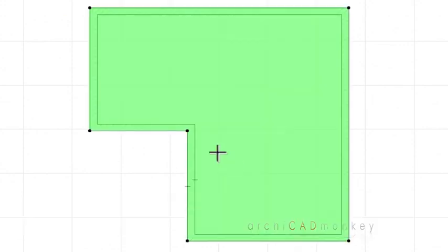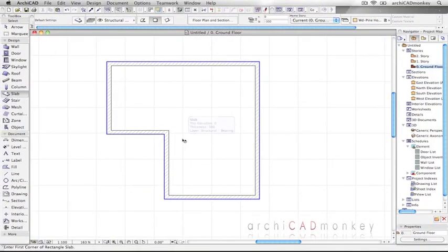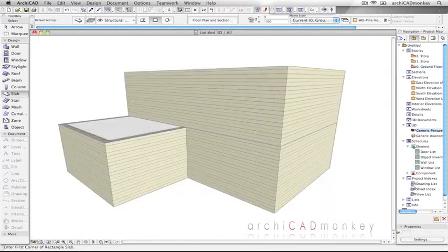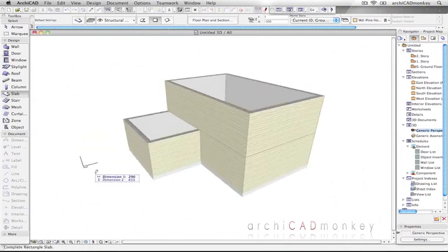So you can draw slabs in the floor plan, just like we did, or even in 3D. On the floor plan, it's not very obvious where they are, as only the outline is shown. On the other hand, in the 3D view, you can see the materials of the slab. Each surface, top, fill, or bottom, can have a different material, or just like the walls, they can be linked to the same one.